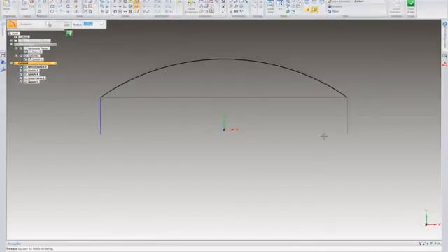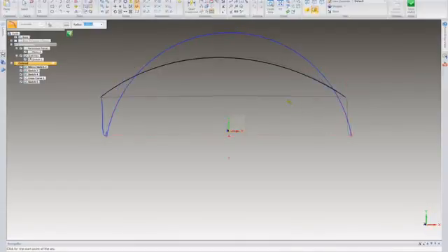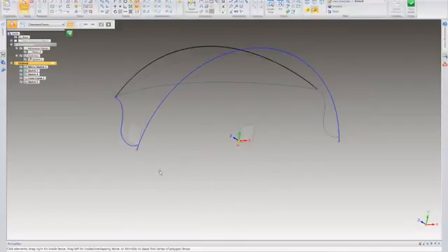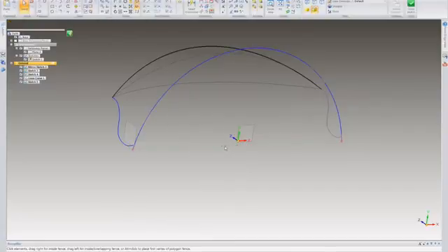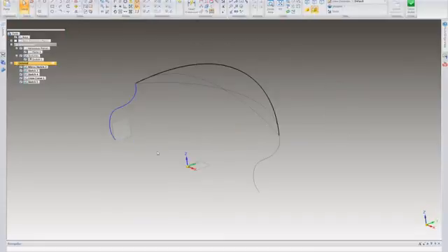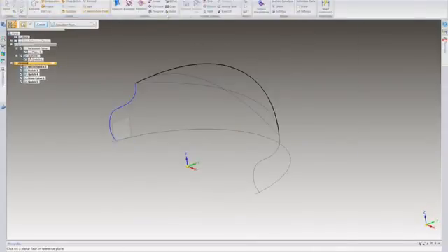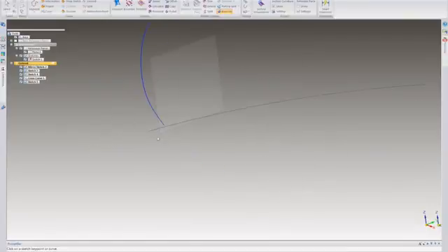And I'll just quickly create that guy. I'm going to go ahead and leave that disconnected just to show you. That's what happens when you don't actually connect in space sometimes. So just to alleviate that, we actually have a command in here called blue dots. All right, so I'm going to come under surfacing and look for my blue dots. All right, so what this allows me to do is it's what they call a semi-destructive function. I'm going to take that corner and move it over to that corner.